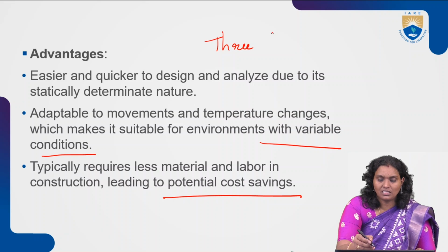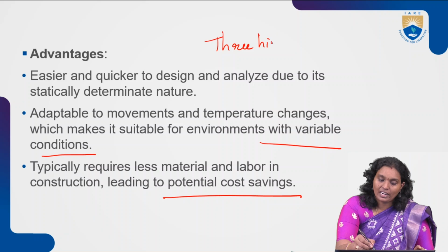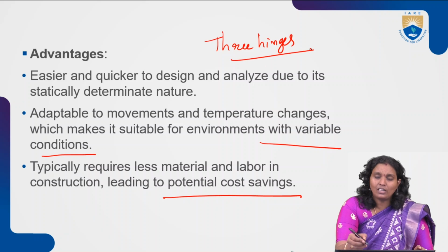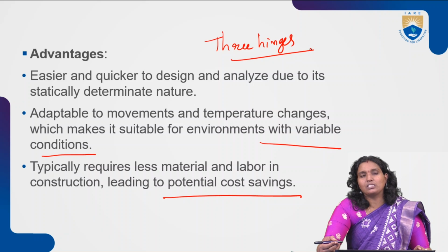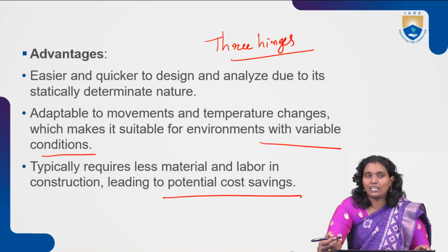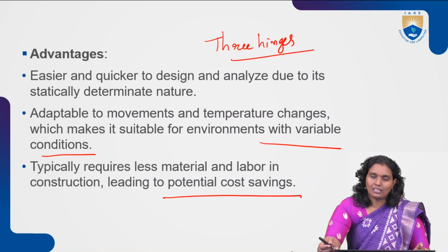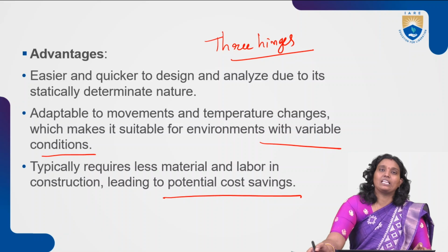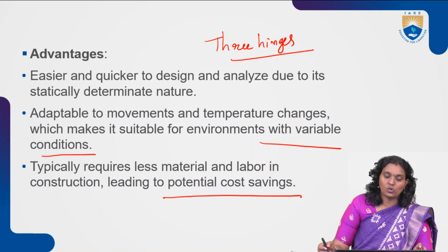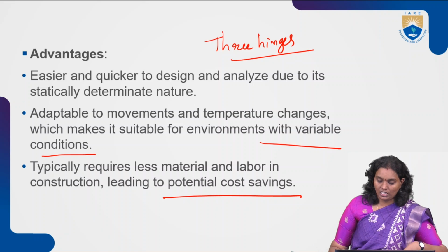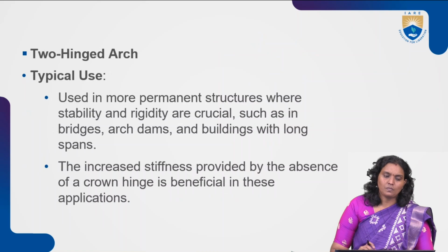From three-hinged arches, the analysis is easy and it is flexible. It is ready for unexpected deformations from settlement. It is going to settle even though unexpected deformations are there. And there is adaptability to movements because of thermal expansions and contractions. And also it requires less material and labor in construction, and saves potential costs.